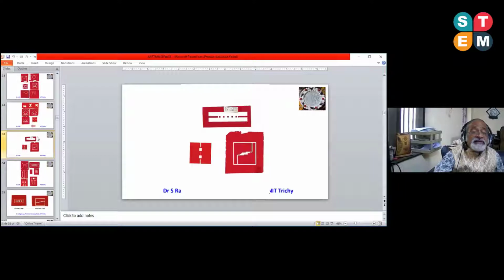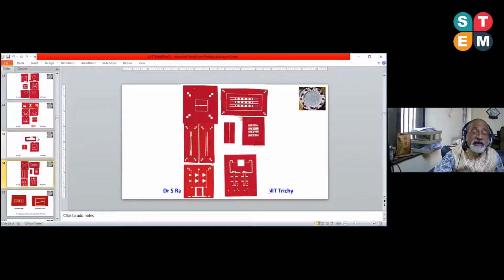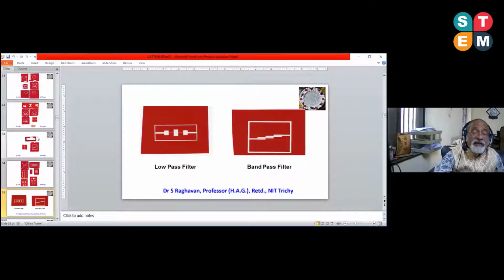This is a bandpass filter. You got a low impedance, high impedance filter. Then the next one is band stop filter, end coupling, edge coupling. Once you are thorough with the components, you can join together, make a system. Again, everywhere, either it will be lambda g by 4 or multiple of that. The whole total length is 2 times of lambda g by 4.